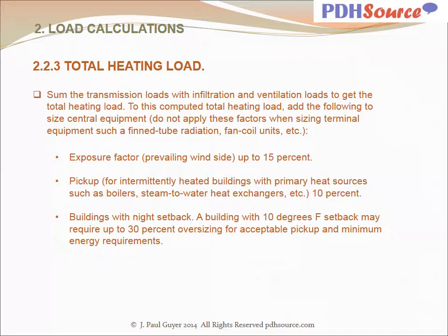And since you don't want the occupants to be in the building shivering for an hour or two before the building warms up, what you might do is turn the heating system on at, say, 7:30 or 7 o'clock and provide some additional heating capacity in your HVAC system to heat the building up quickly and get it up to a nice comfortable condition.